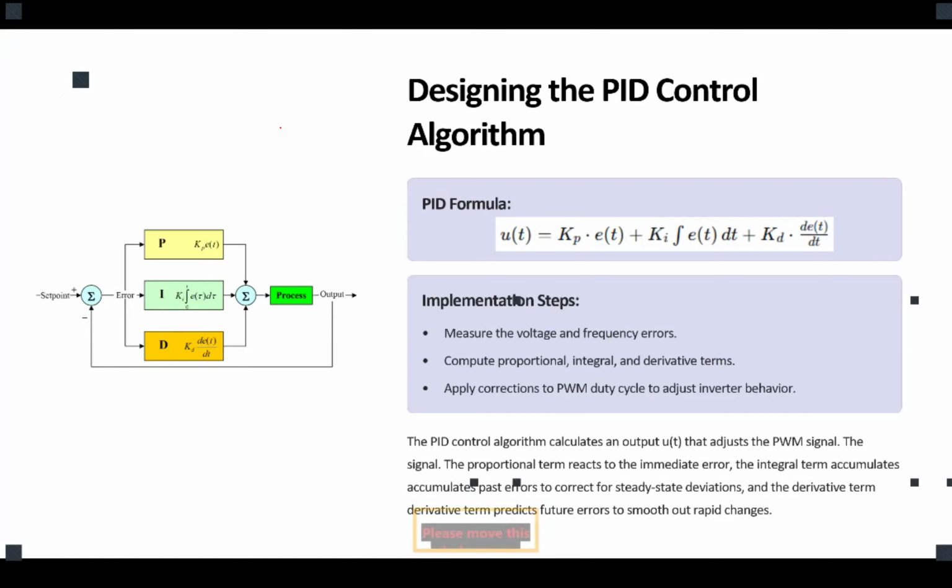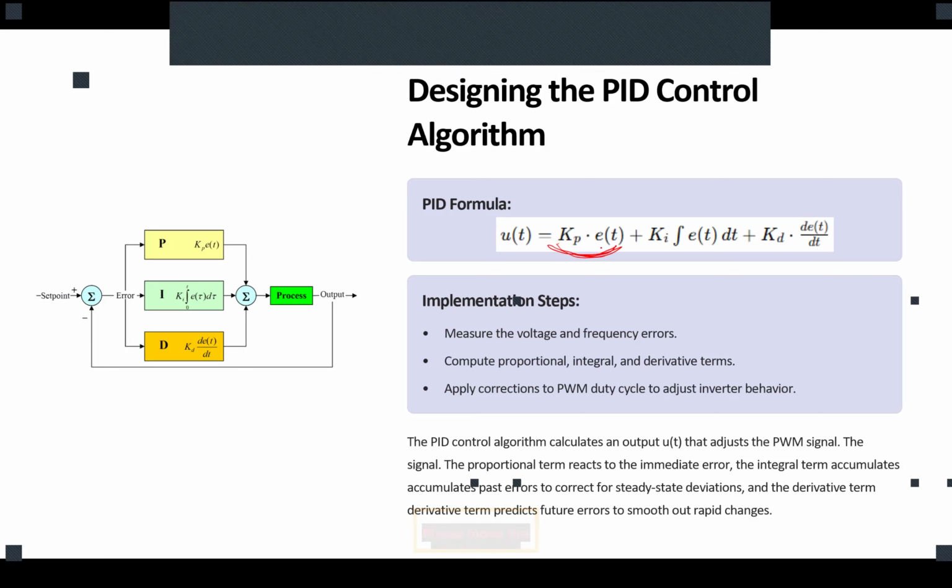Okay, actuating kind of a signal. Now we have three terms. One term is proportional. Based on the name, it means it simply reads the error, applies a gain, and we have our proportional portion of our control signal. The first step. Let me show it so people in the Zoom meeting can see it also. We calculate the error, we add a gain, and we have our proportional portion of our control signal.